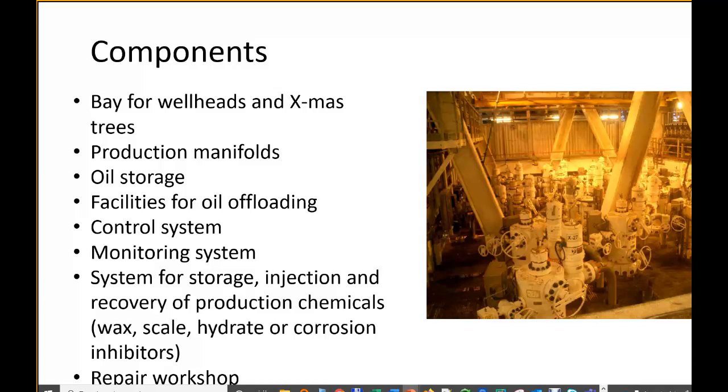And that drilling tower usually has a way that it can move to be exactly on top of the well. It has some skids that it can slide on, and can be placed just on top of each well. That also has a problem: if you are doing an intervention or something in a well, all the other wells usually have to be shut in. Okay, they have to be closed.